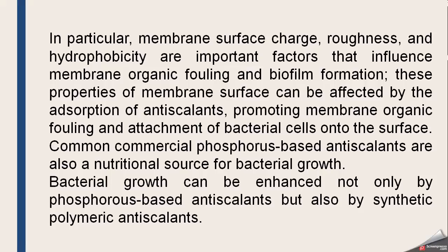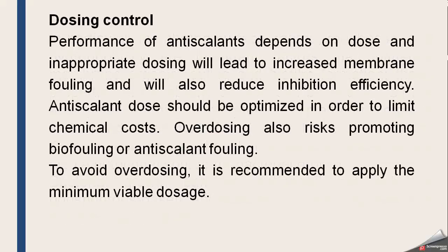Common commercial phosphorus-based antiscalants are also a nutritional source for bacterial growth, and this is enhanced not only by the phosphorus base but also by synthetic polymer antiscalant. So this is one of the major drawbacks, and we have to focus on dose control. If we add a higher dosage of the antiscalant, definitely it will increase the biofouling. So dosing control is important, and the performance of antiscalant depends on dose. An inappropriate dose will lead to increased membrane fouling, or if we dose a lesser amount of antiscalant, then the efficiency of the inhibition will reduce.